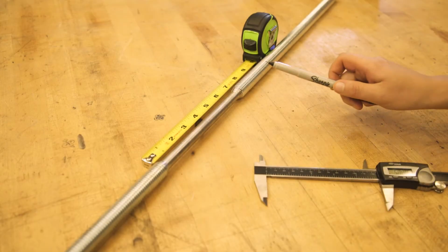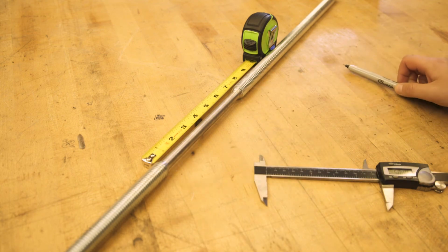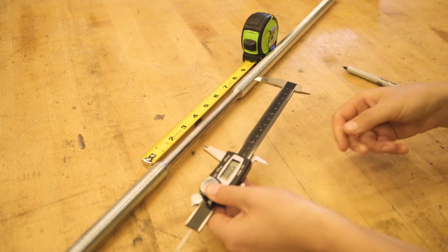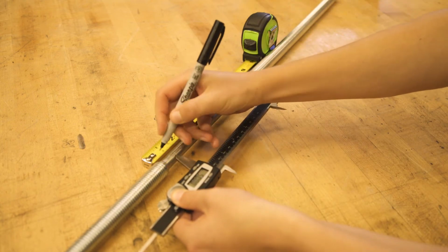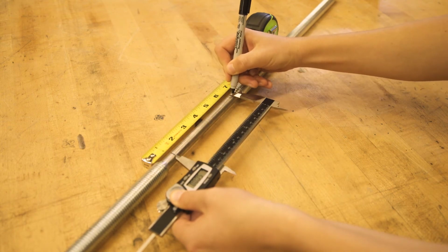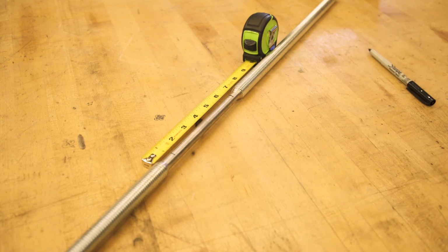The cross-sectional area of the specimen is smallest near the specimen center to ensure failure within the gauge length. Measure the length of the reduced cross-section within the specimen. Mark gauge points to create a 5-inch gauge length near the specimen center using the calipers and the marker. The purpose of the gauge marks is to determine the percent elongation after failure.